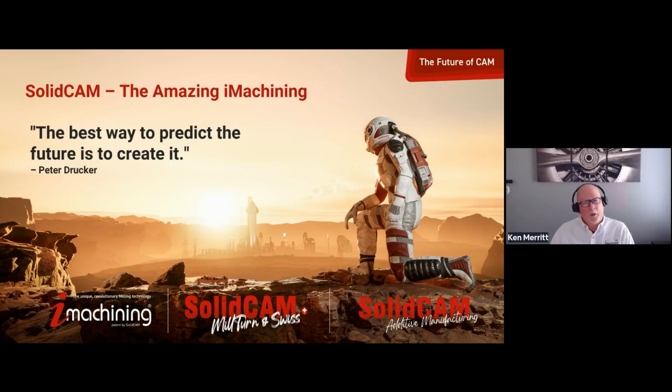There are several things that really separate us from everybody else in the industry. Number one, because of the way that we are calculating the engagement angle, the cutting angle, if you will, and because of how we're managing the morphing spiral, ranging that angle from a minimum to a maximum all the time so that that spiral can morph from one shape to another, we are managing the feed rate simultaneous with all of that so that at the actual cutting angle, the chip thickness never varies.